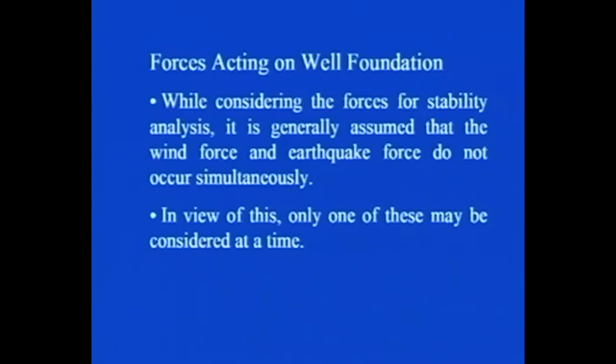While considering the forces for stability analysis, it is generally assumed that wind force and earthquake force do not occur simultaneously. So, since they do not occur simultaneously, only one of these may be considered at a time. So, if you are considering, let us say, wind force, then you may not consider earthquake forces, and vice versa.